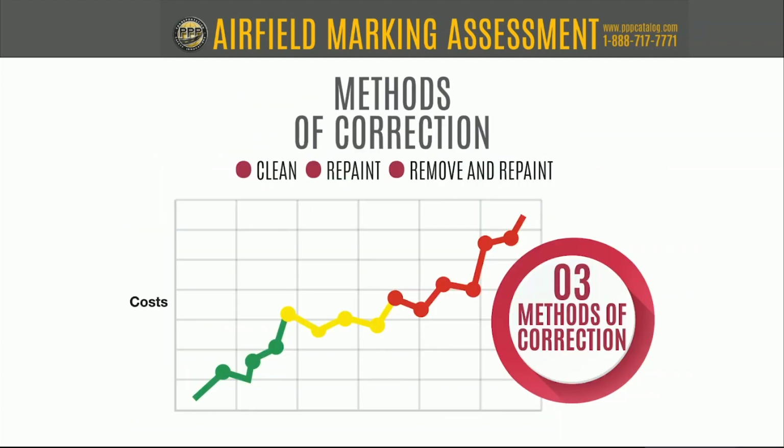All right, now let's move on to the methods of correction. So typically you're going to have one of two problems, because that's what's in the specs, right? You're either going to have a deviation of retroreflectivity that goes above that 30%, or you're going to have a retroreflectivity problem, which is when that marking is below the minimum retroreflectivity. So there are basically a few methods in which we can correct that. And I'll let you start us out there, Mike.